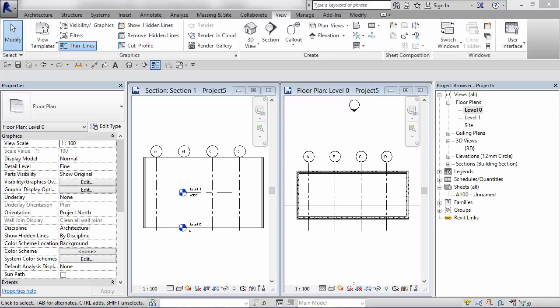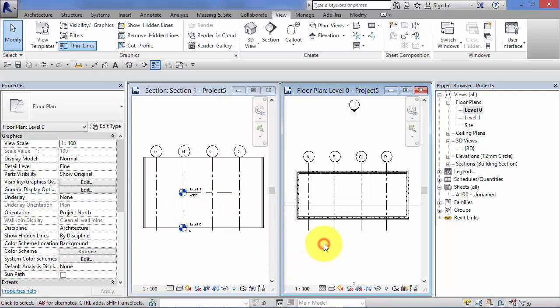Many building designs utilize a structural grid, and luckily in Revit we have a structural grid tool. Just before I show you how to create the structural grid, I just want to show you a really powerful feature of structural grids in Revit, and that is the fact that they are 3D planes in their own right, which means they stay coordinated between different views.